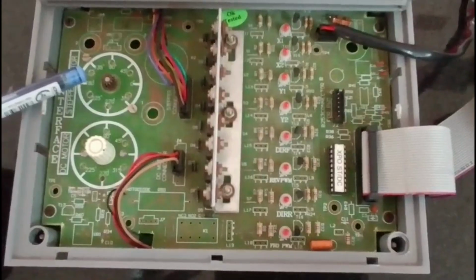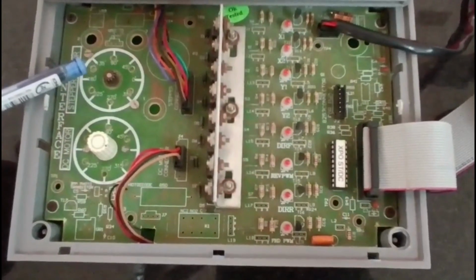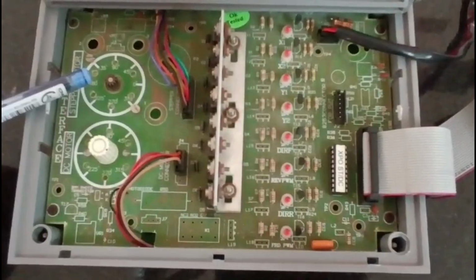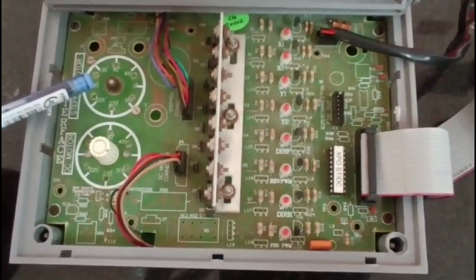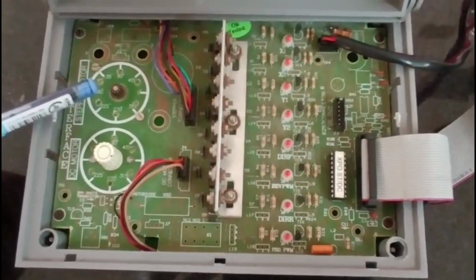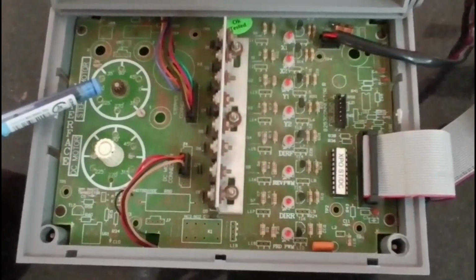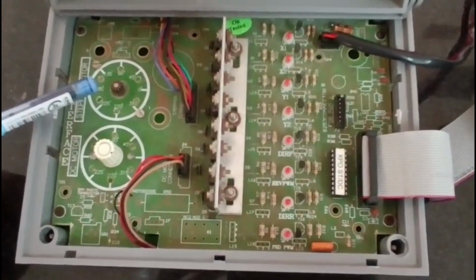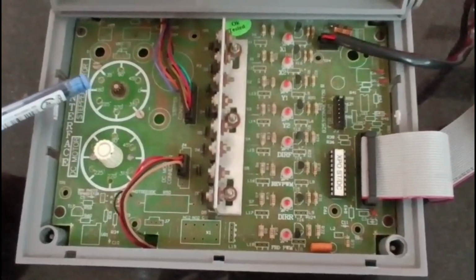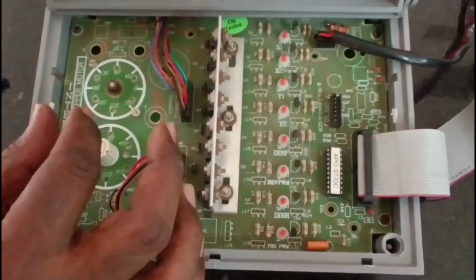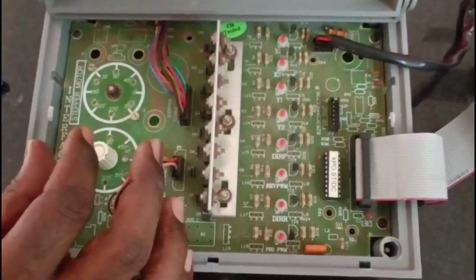So this is the stepper motor. Actually the stepper motor is a special type of DC motor. It is a permanent magnet or variable reluctance DC motor. It is an electromechanical device which converts electrical DC voltage pulses into discrete mechanical movement. The shaft of the stepper motor rotates in discrete steps when electrical command pulses are applied in the proper sequence.